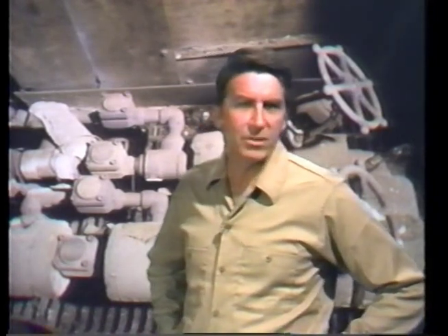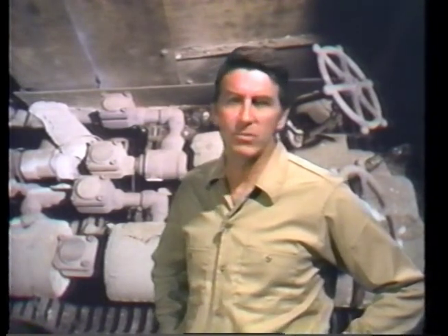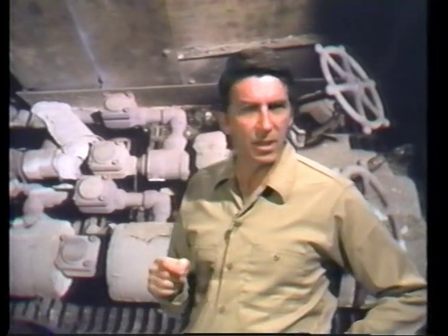Failure of thermodynamic traps in the closed position, where you would hear no sound at all, is rare. But if the trap does not seem to be opening or closing, you can usually open the strainer blowdown valve and sample the contents in the pipe leading to the trap. If the blowdown line passes a lot of condensate, but the trap doesn't, the trap has probably failed shut.